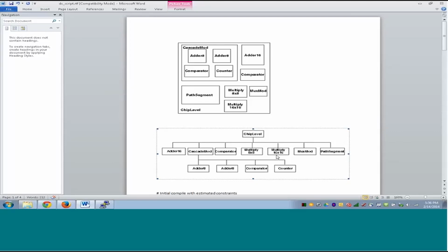So if you are confused about which synthesis methodology to take, the Design Compiler capacity, the number of cores in the machines and the memory in machines have been growing. So every year it's getting more possible to compile a design top down, which was not possible or not practical a few years back.